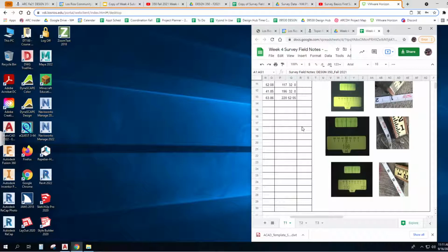Okay. And so, yeah, I know I'm giving you the answer here. You still have to do it. You have to draw it. But we'll also have some more that I won't demonstrate, and you've got to get those answers in. But these are the 3 data points. Distance, bearing, distance, bearing, distance, bearing. And remember, I've told you that our theodolites measure degrees clockwise.